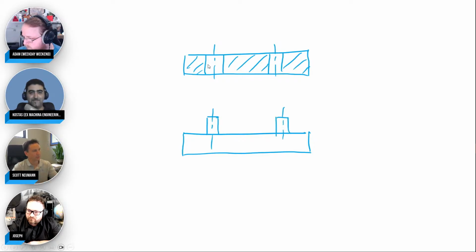How do I make sure that these holes will not be off position too much where they accept the pins? And it's real easy. Smallest hole, biggest pin. And then when you do your position tolerances, the tolerance zone always applies the length of the feature. So you get a cylindrical tolerance zone on this one, you get a cylindrical tolerance zone on this one. Now, when you insert that pin into the hole, the tolerance zones overlap each other. So it's just a really easy smallest hole, biggest pin, split it between the parts. It's simple.